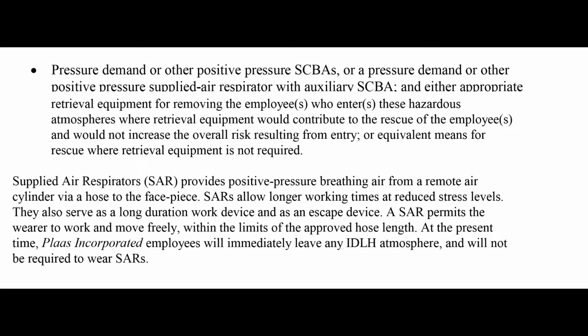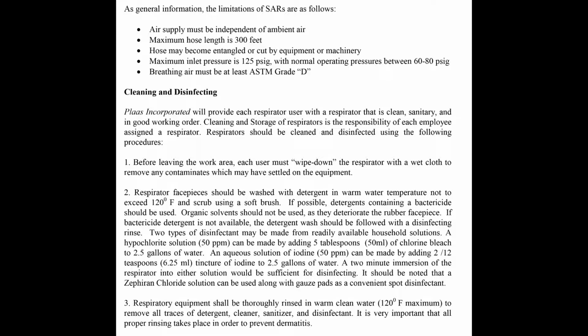Supplied air respirators, SAR, provide positive pressure breathing air from a remote air cylinder via hose to the facepiece. SARs allow longer working times that reduce stress levels. They also serve as a long-duration work device and as an escape device. An SAR permits the wearer to work and move freely within the limits of the approved hose length. At the present time, Plaas Incorporated employees will immediately leave any IDLH atmosphere and will not be required to wear SARs. As general information, the limitations of SARs are as follows.